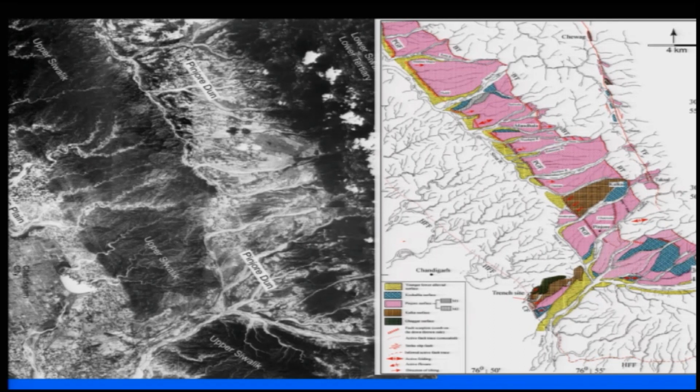So if you have usually the alluvial fans, then from here if I put the topography, you will have something like this. The slope will be in this direction, but what we see here is that at some locations, for example this portion, there is tilting in this direction. If I take the section here, it looks something like that. So it has a back tilting. These have been termed back tilting scarps.